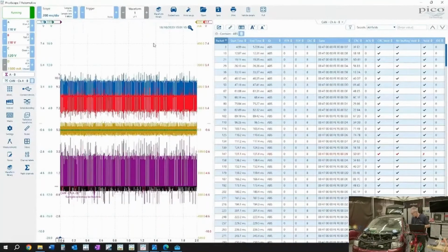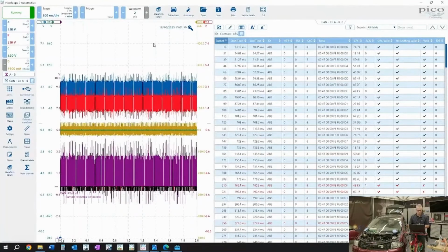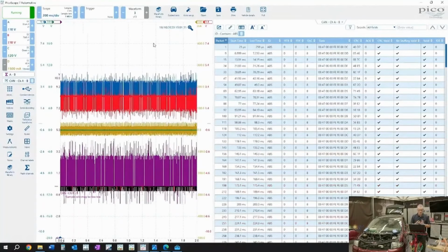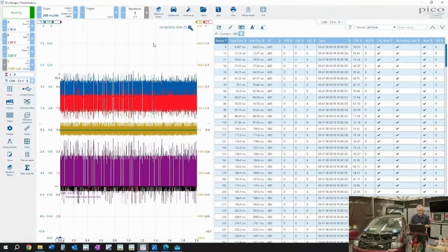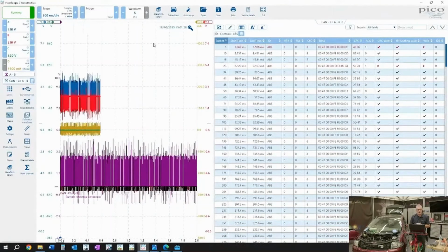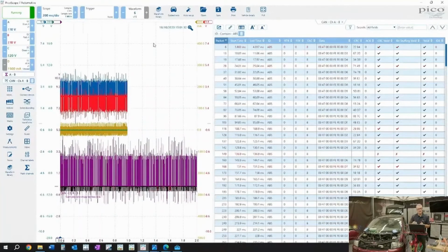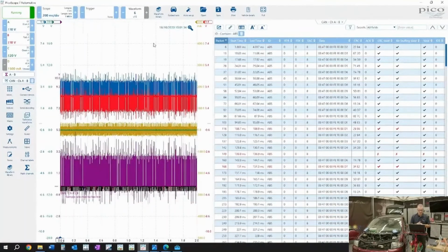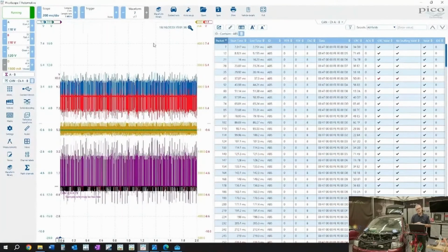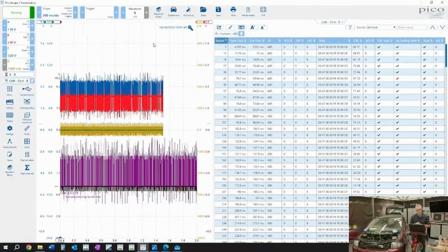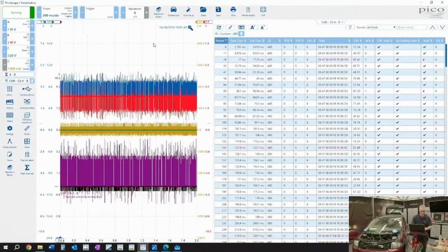One of the CAN wires, I think it's CAN low, yeah, CAN low at the ABS ECU. What I found really useful, and Ben has done a great video on this, he's actually using our current clamp to determine who is sending the signal and when. So because it's going to the ABS ECU, when the ABS ECU transmits something on the CAN network, we can catch it with the current clamp. And we'll prove that now.